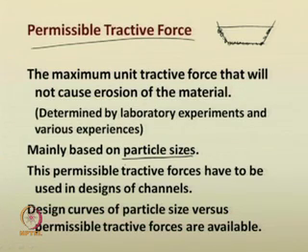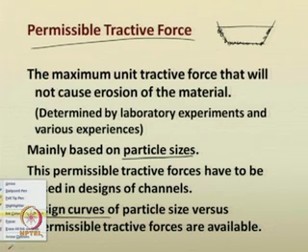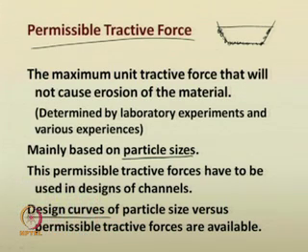So, these permissible tractive forces you can easily apply in the design of channels. There are various design curves available, particle size versus permissible tractive forces, and you can use them. You can refer to many books or hydraulics bulletins to get the permissible tractive force for a particular material.